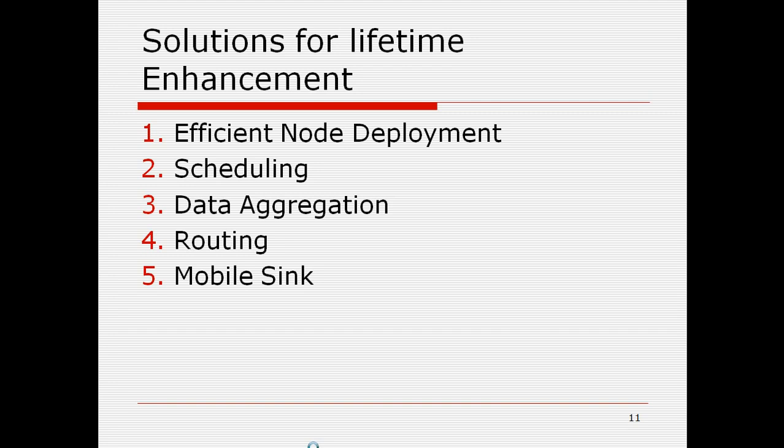So scheduling means sending data to the base station in a proper way. We do not sense temperature and send data every 1 minute. We sense the temperature now, then again after around 1 hour or 3 hours, when the change in temperature is not too small. This is defined by scheduling.